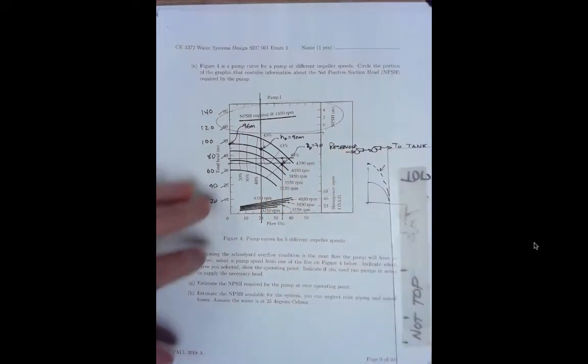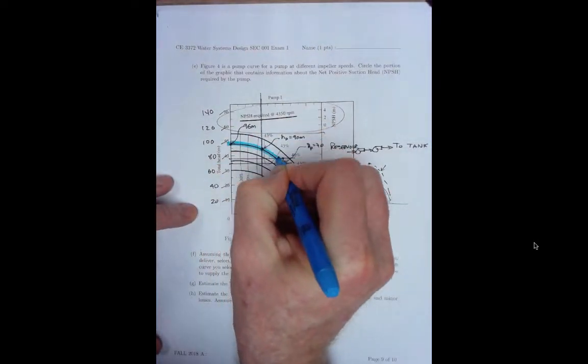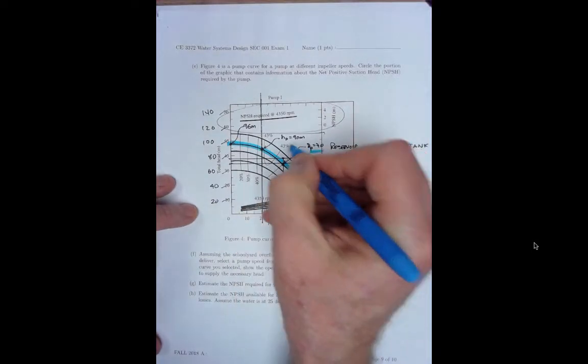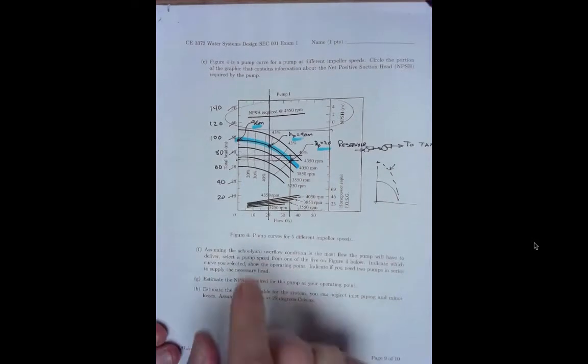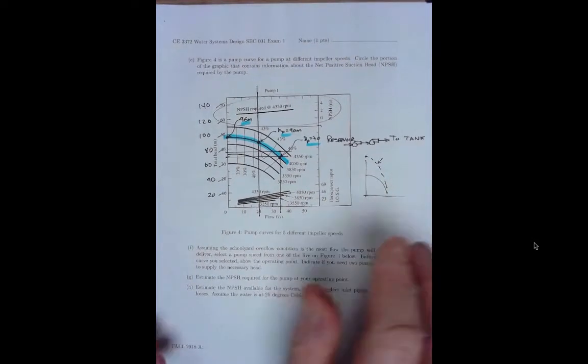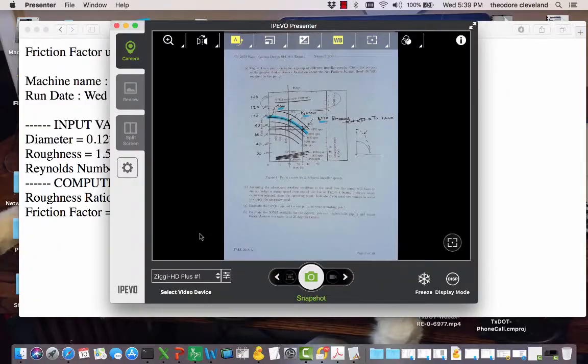70 meters of head. So my pump curve for 2 pumps in series is going to be that, and it's going to have these 3 points. Now the reason I'm doing that is I have an online tool that allows me to enter a 3-point pump curve, other parameters of the system to see how well it's going to function. So let's use that tool.